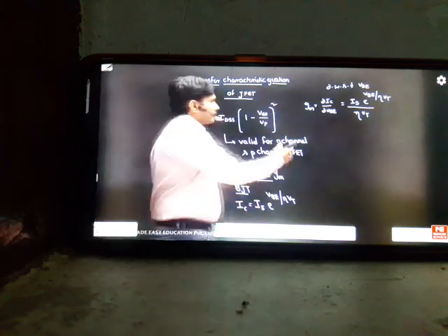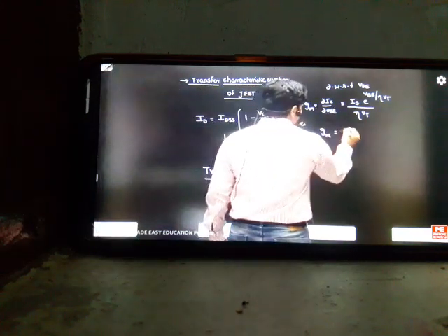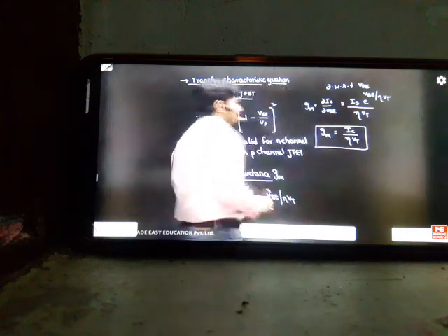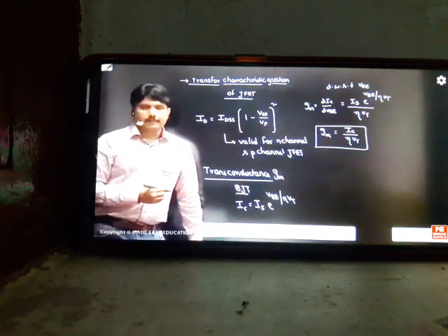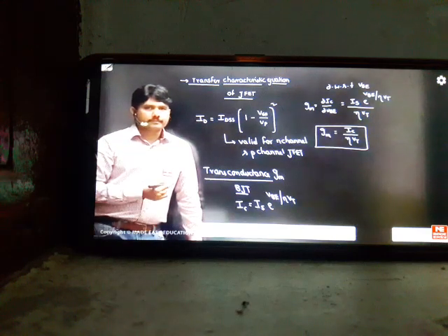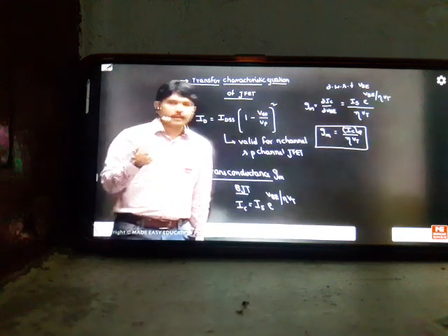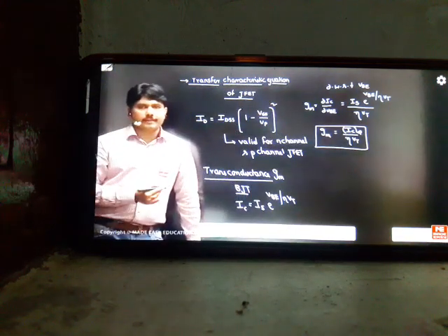So this equation can be written as gm is equal to IC divided by eta VT. This is called BJT gm from now onwards in electronics. So in future classes, don't keep surprised faces, okay? When I'm teaching the design part, gm will be normal for me in the classes. gm always depends on your operating current, which is your DC current. From the biasing circuit, you have to calculate the operating current called ICQ. Only then can we find gm in amplifier circuits.